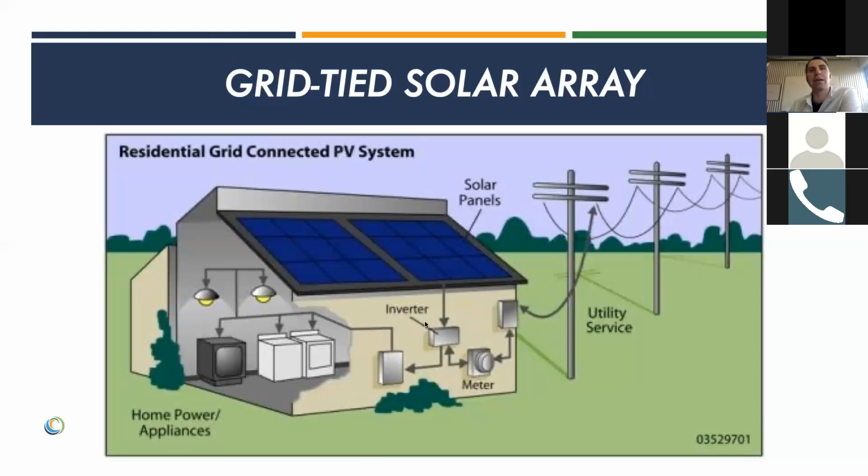And we're going to be talking about that because first I have to preface this with how a normal house works. So in a normal home, electricity comes in here off the power lines, off the grid, it goes through your meter, and then it goes through your circuit box and out into your appliances. In a home with a solar array, the sun hits those solar panels. Again, the solar cells create DC or direct current. That direct current electricity then flows down to your inverter. Your inverter converts it over to AC electricity, which goes again through your circuit box and then again out into your appliances and your lights and your other electrical gadgets and gizmos.